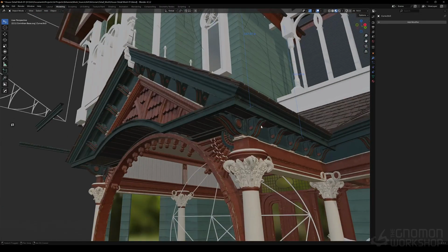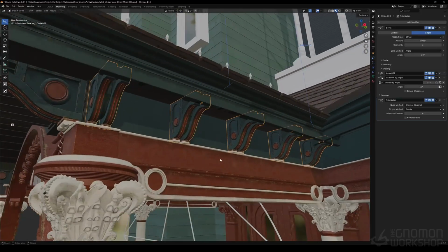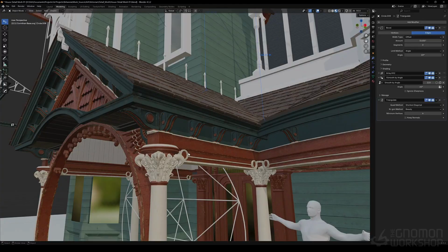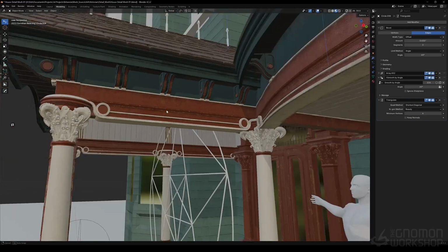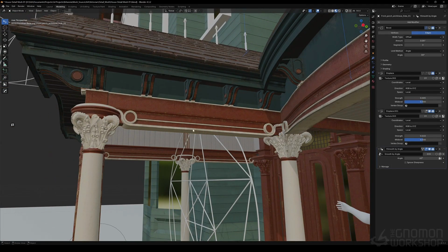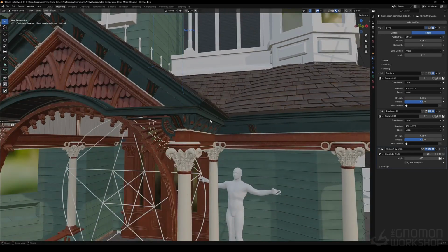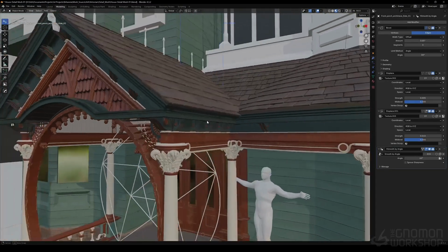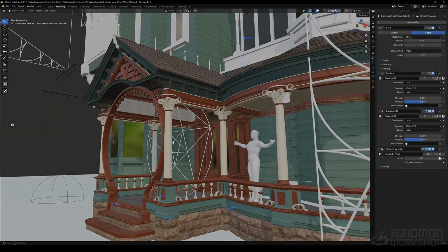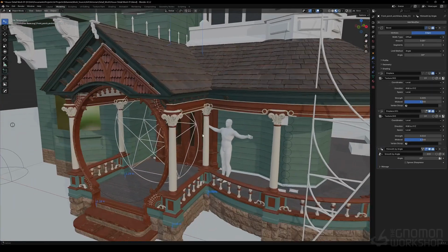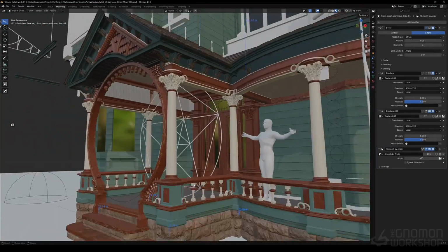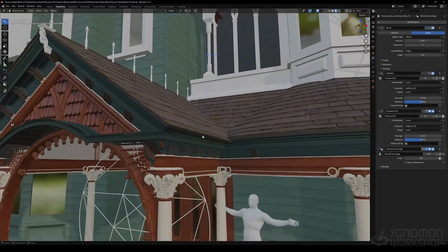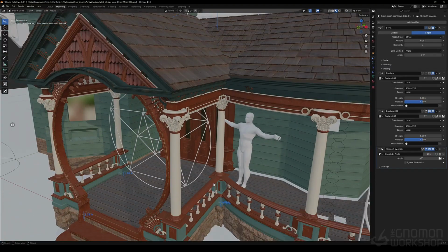Additionally, I have other elements for decoration, like more corbels. These aren't really needed structurally, but again, we're using decoration and ornamentation to abstractly reference the concept of holding things up. And then because of that, we are drawing attention to the architrave beneath, which is this beam element. And then, of course, the roof above. This extrudes out because of rainfall. So despite the fact that all of this looks quite decorative and ornamented, at the very foundational level, all of these components are referencing typical architectural concepts like support, frames, and then shedding water from your structural elements.